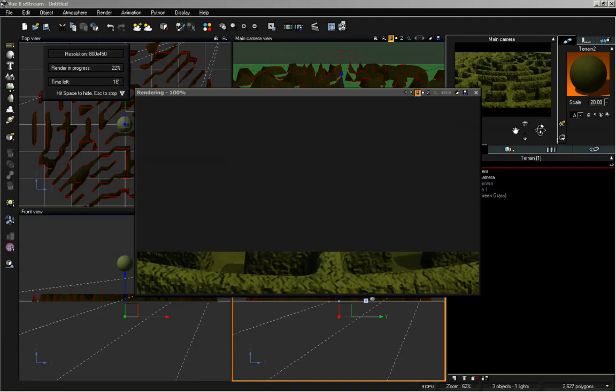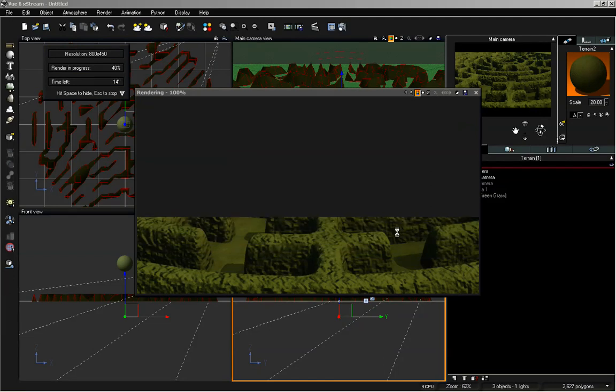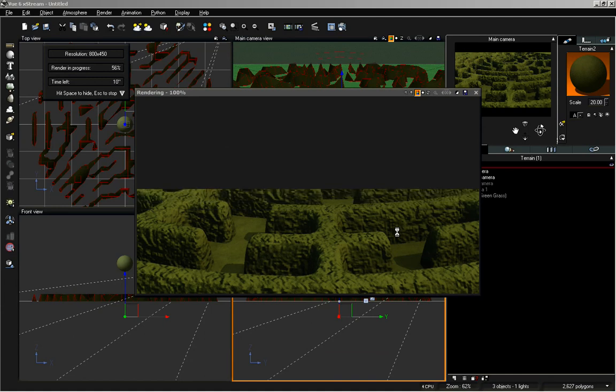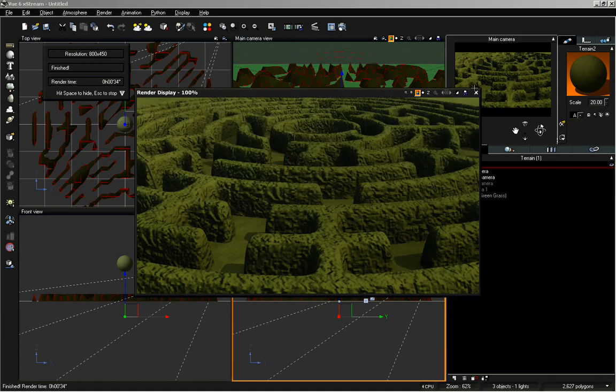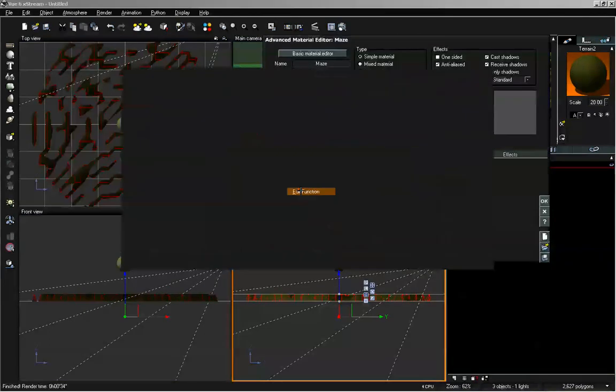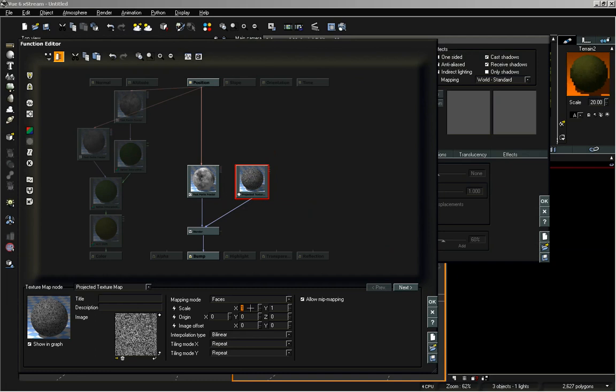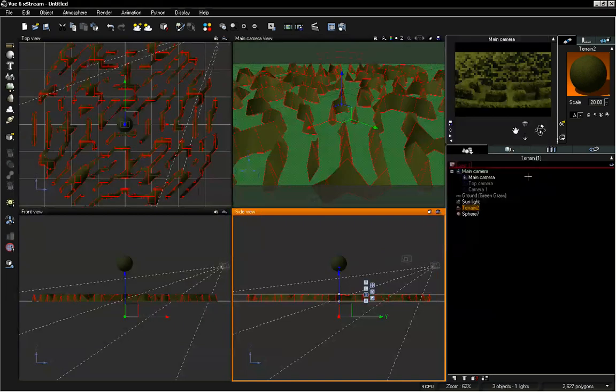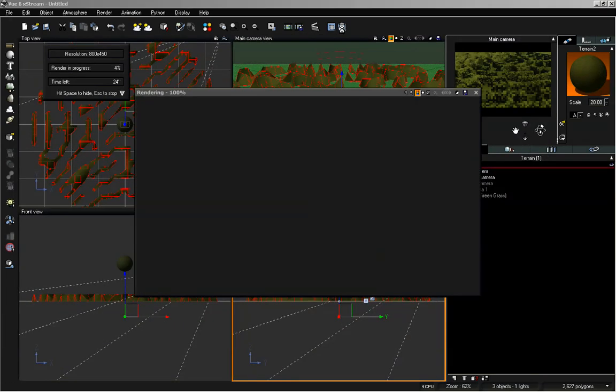And we can already see with this rendering all of our bumps showing up from the bilinear interpolation, and that means that our image is way too large. So we'll go ahead and open that back up, and I'm going to change the scale to 0.1 on the X and the Y, and we'll see how that turns out. We may need to adjust its strength.